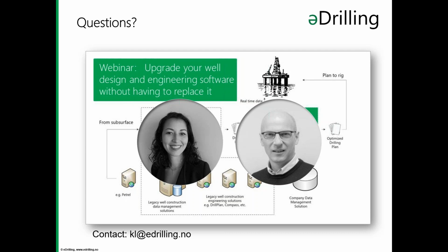Okay. Another question is, what data do you require to configure your system when it's used as a microservice? So for this one, we need a drilling plan with the suggested flow rates, the movements, and so on, and also all the well configuration like the BHA, the trajectory, the geometry, etc.